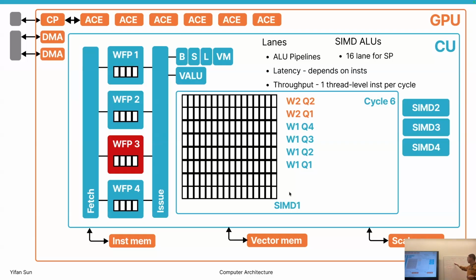But consider the number of lanes. This is 16 lanes, this is 32 lanes. So lanes per CU here is 64, here is 128, right? Just a multiplication. Because of this, one NVIDIA SM is more powerful than one AMD CU. It's almost double the amount of calculation capability.